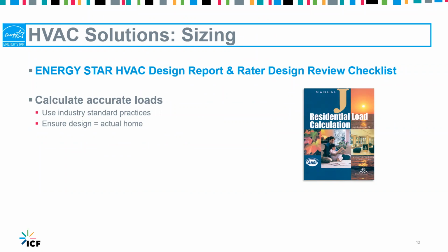But there are also things that I talk about that go above and beyond Energy Star requirements. For sizing, use industry standard practices like ACCA Manual J. Make sure the design of the home accurately reflects the actual home, that it's the right size and has the right amount of windows, so they're comparable and close to each other.